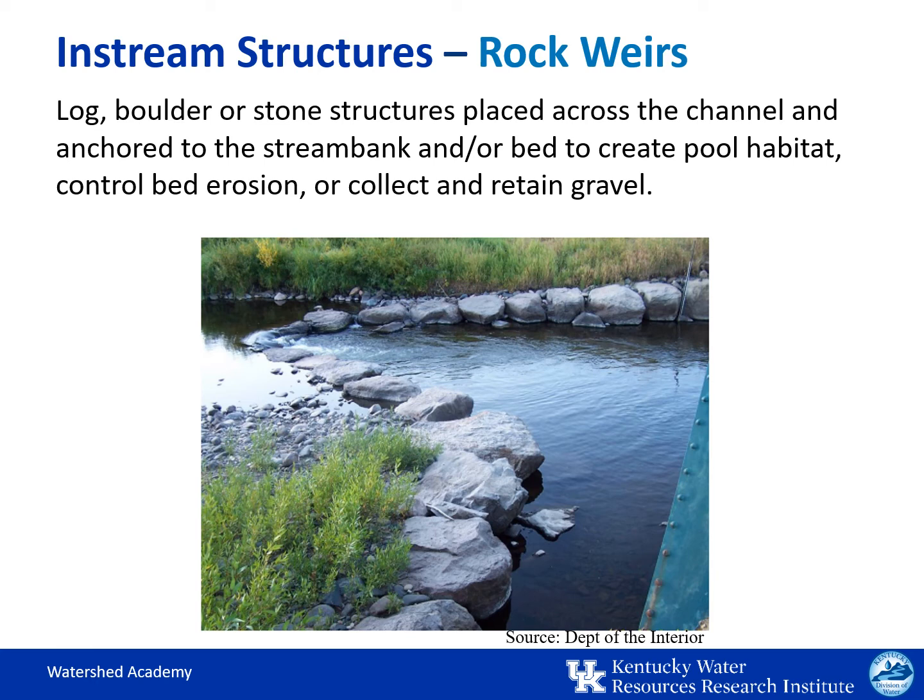Whereas during high flow, the water rises over the stones, creating a scour pool below the structure, but allowing sediments to move through. Again, these weirs can be constructed from logs, and like rock weirs, log weirs provide bed form diversity, maintain the channel profile, and provide pool and cover habitat.